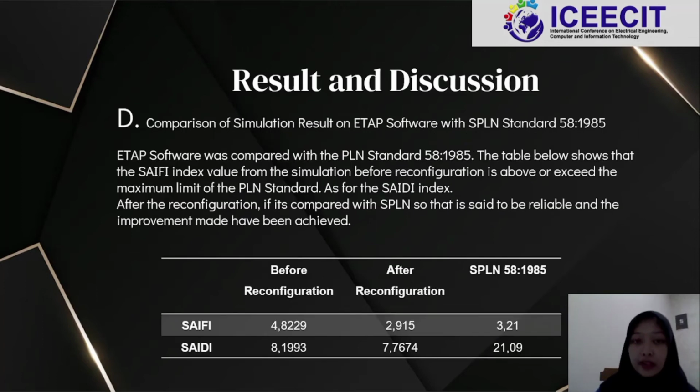The fourth point, comparison of the simulation result on ETAP software with the PLN standard. The table below shows that the SAIFI index value from the simulation before reconfiguration exceeds the maximum limit of the PLN standard, as for the SAIDI index. But after the reconfiguration, when compared with the PLN standard, it is said to be reliable and the improvement may have been achieved.